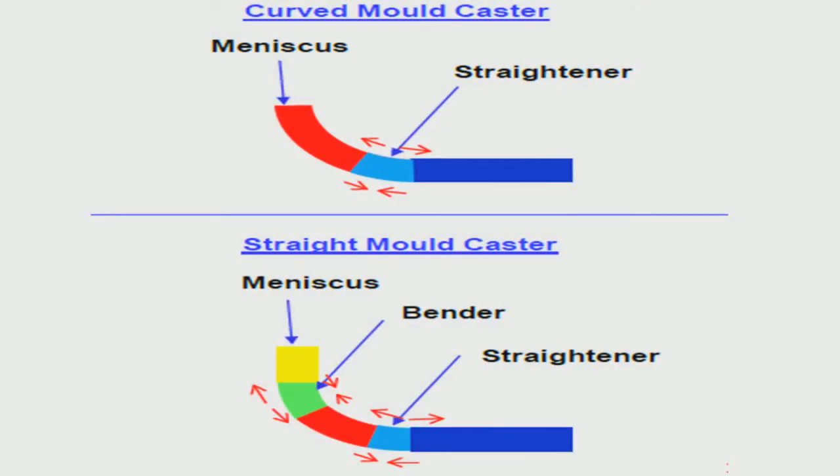Another important issue let me talk about during continuous casting, which can generate problems of entrapment at certain locations. I have mentioned earlier that continuous cast product does not have a uniform quality. Certain portions of the casting are relatively inferior in quality. I have mentioned that at the start of casting and the end of casting, at the changeover, at the stage of sudden fluctuation, there is a possibility of entrapment. So, those areas are relatively inferior.